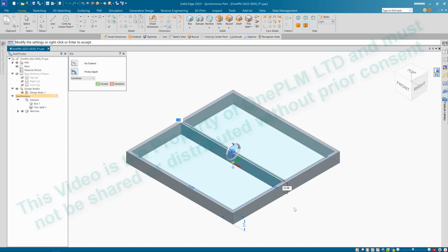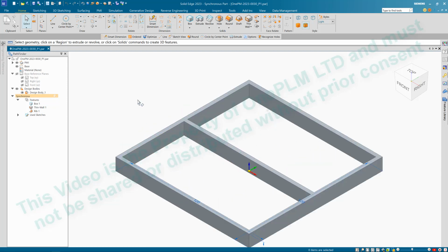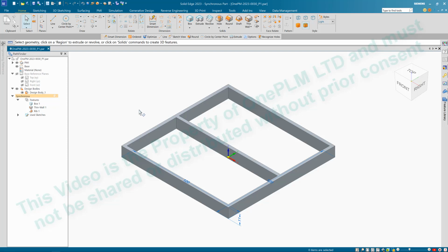If ever we get that kind of option showing that size is wrong, so if I go back to 50 or something on there, grayed out means it can't do it because the rib doesn't support that. So we can use tab to go between those different values and set that. Grayed out means that there's some kind of value input that's wrong, that's not allowing us to do what we want. Okay, so that's got our model on there.